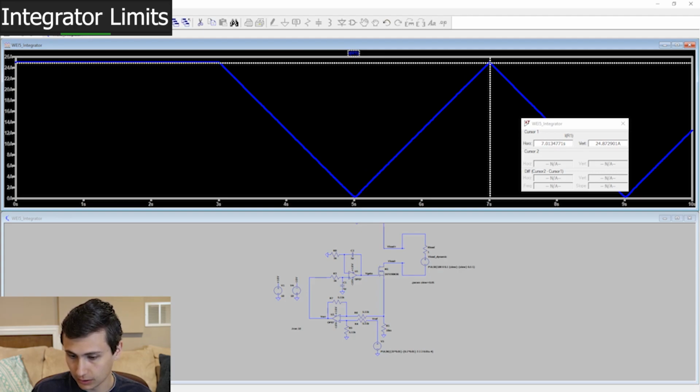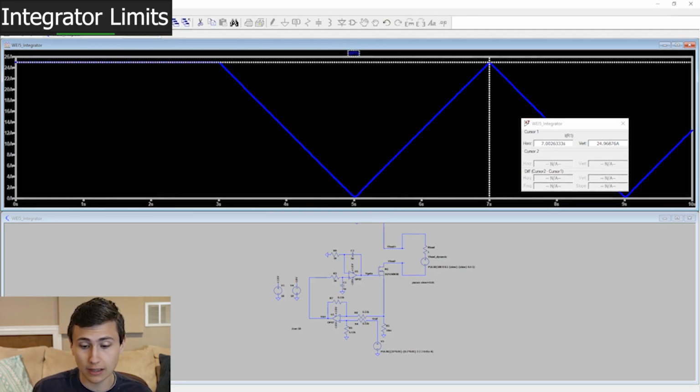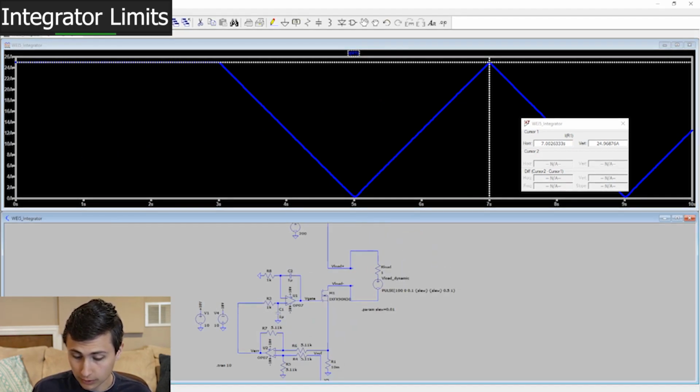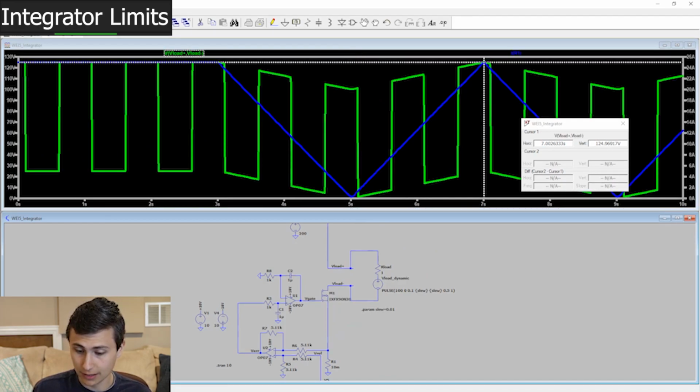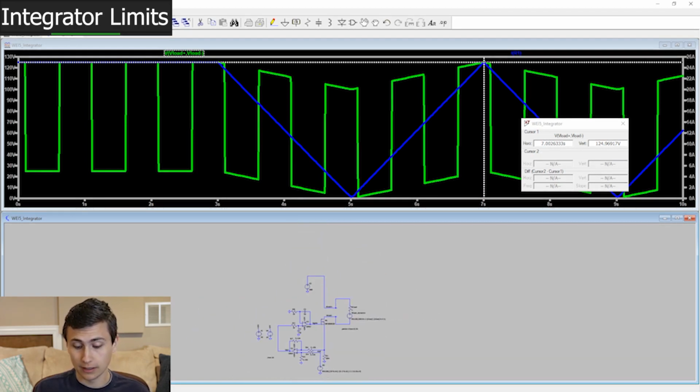And yeah, you notice when we're in that triangular region, we don't quite get to either one because the integrator doesn't have time to dwell to actually settle out and reach that zero error state. It takes a while to actually settle out to that zero error state. But we are still doing that phenomenal transient response where we're giving very sharp edges, but the current regulation remains. Again, very large amounts of power dissipated in that MOSFET.